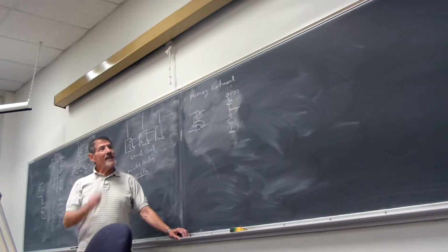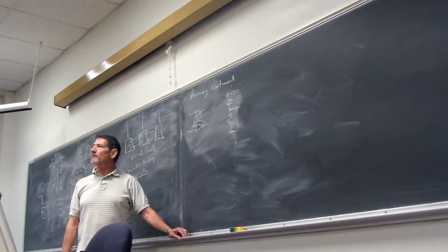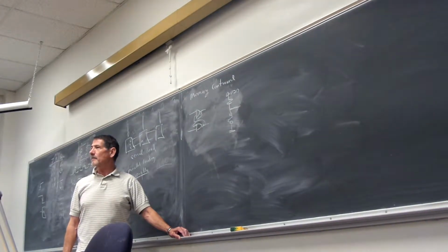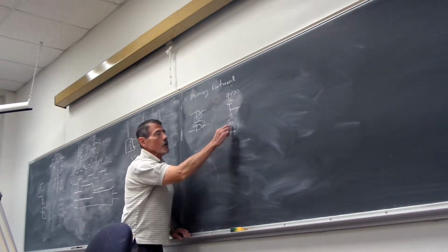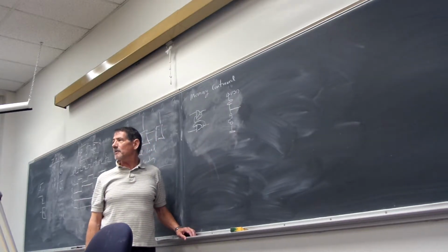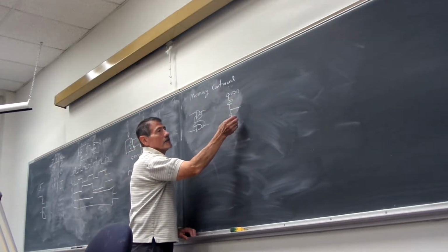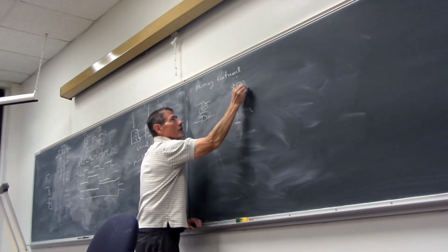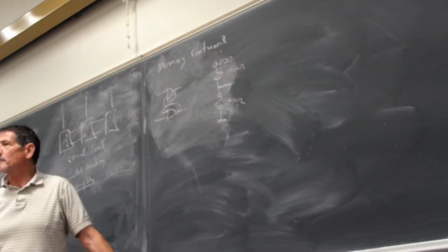All right. So in this state here, if this is a memory cell, what variable is at the output? Now wait a minute. That's a fairly large resistor. What would you expect the on resistance of a fuse to be? Pretty low. So let's take something low. Let's go with 400 ohms, and we'll make this 100 kilo ohms. Okay. So what voltage approximately do I have out?